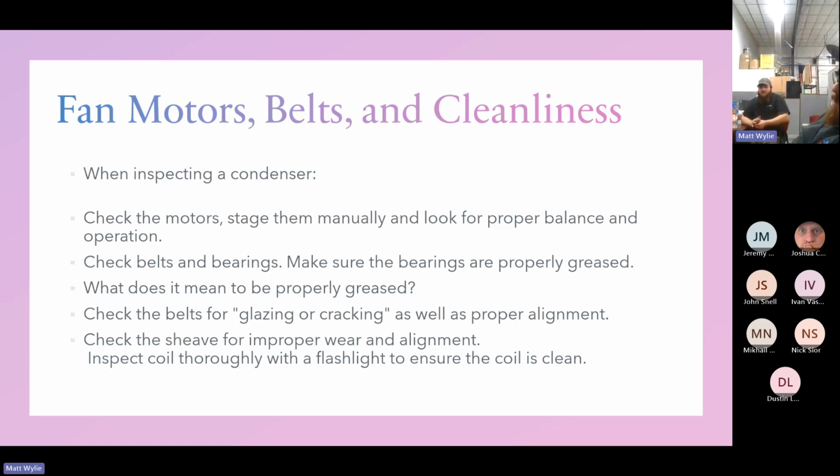And just like Idaho Falls, Ammon here, we have extremely hard water. So if you have a water source condenser, chances are that sucker's run for 10 years and that coil's all gunked up and plugged with stuff. So there's nothing you can do.